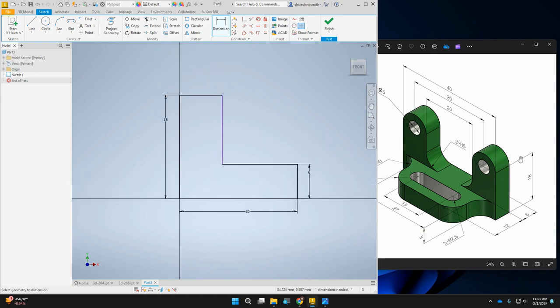And now I got to draw my circle. This is very common where we have an arc that goes right into a vertical feature. This is a tangent feature. So I'm going to create a circle. The easiest way to do it is put it on the middle and then grab the edge. You'll notice this little thing that shows up above my mouse is the tangent constraint. If I didn't do that, I can hit tangent, circle to the line. Okay, so that's going to create that.